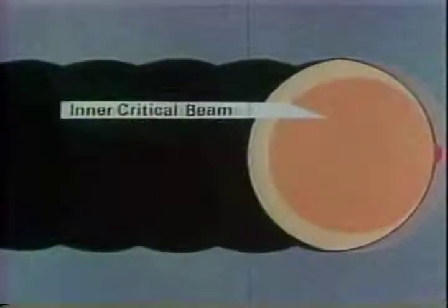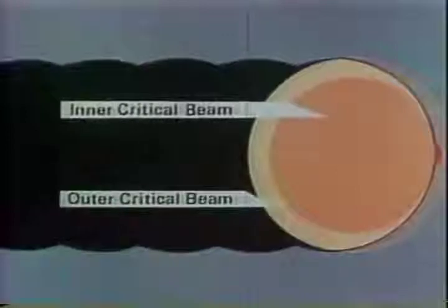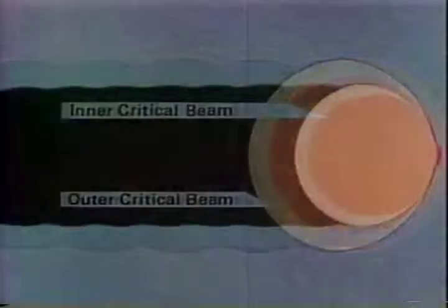Here, the orange beam has the minimum energy necessary for reignition and is called the inner critical beam. The yellow beam has the minimum energy for self-sustainable reaction and is defined as the outer critical beam. Each beam, especially the outer critical beam, decreases in diameter with travel speed. Accordingly, the curve becomes narrow. When the beam travel speed is balanced with the reaction rate, the yellow zone disappears and continuous burning is self-sustained, thus leaving no striations on the cut surface. Let's explain these in detail.